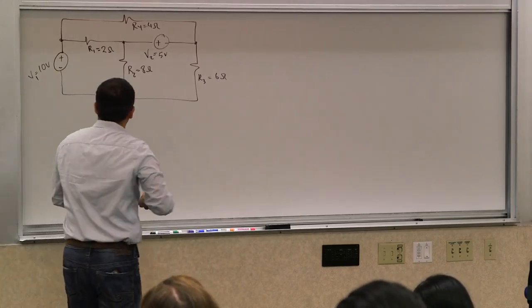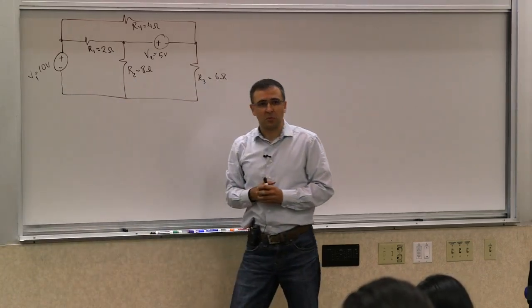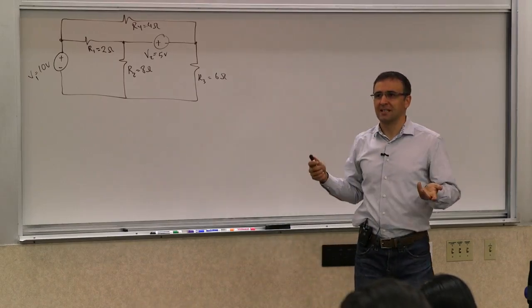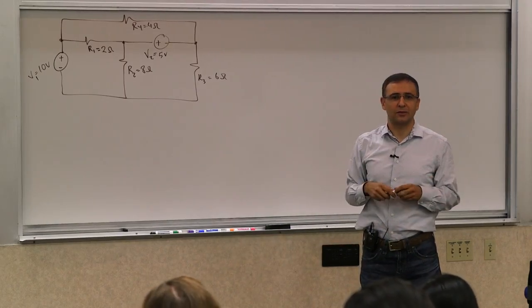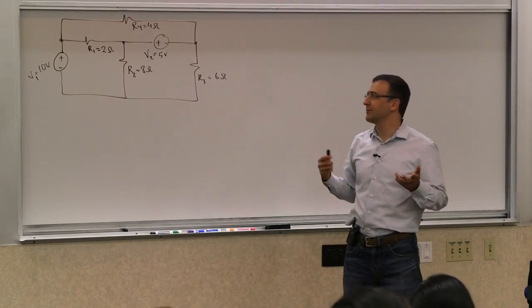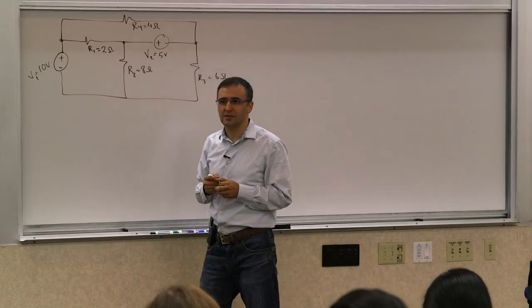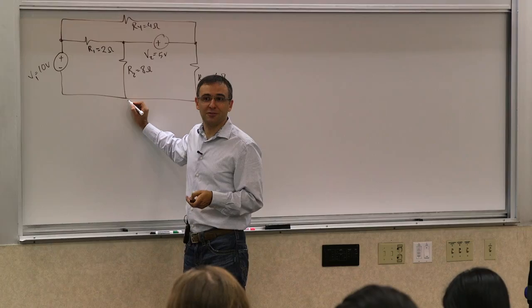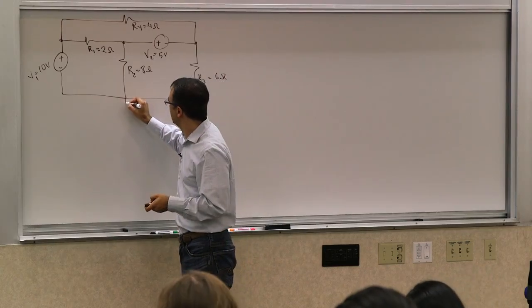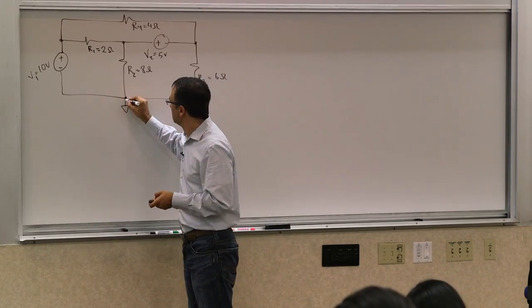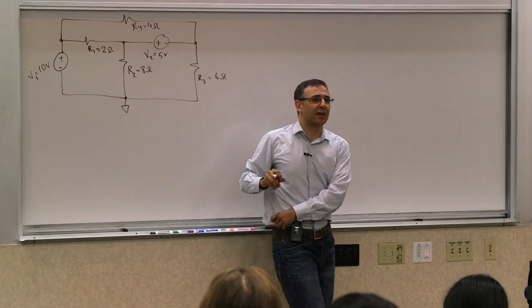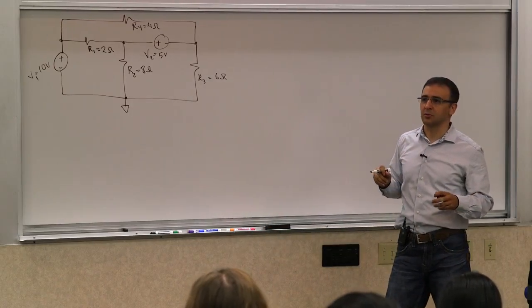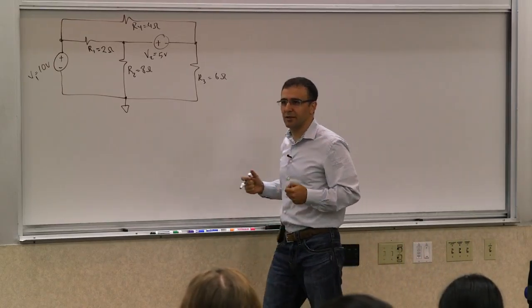So how do we deal with this? Let's go through our procedure and see if it gets us anywhere or where we get stuck. The first step of the procedure was to define a ground, a reference potential. I recommend this, unless you disagree. But again, nothing fatal will happen if you choose another one, just your life becomes a little bit more difficult. Builds character.